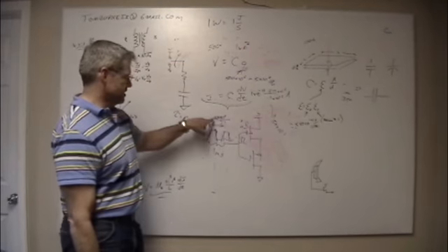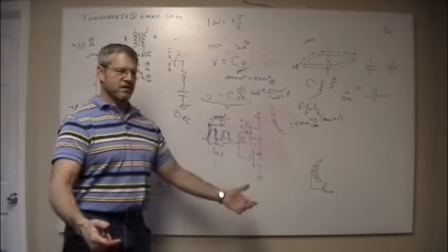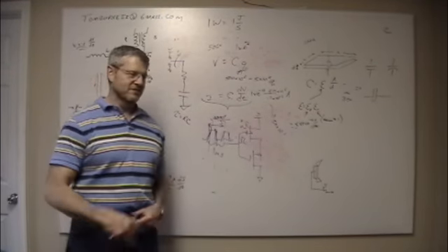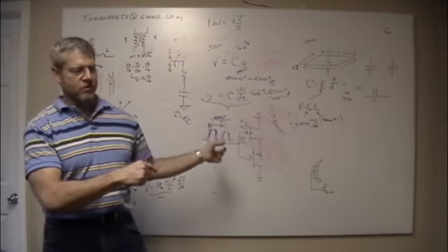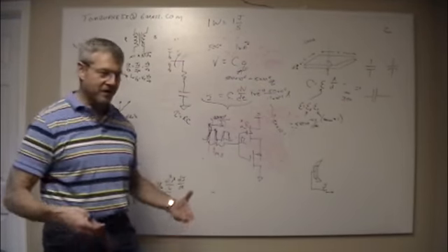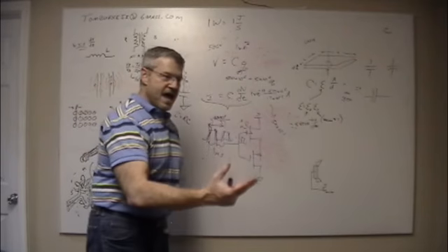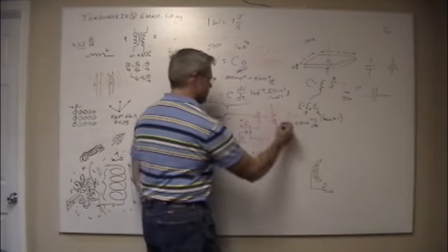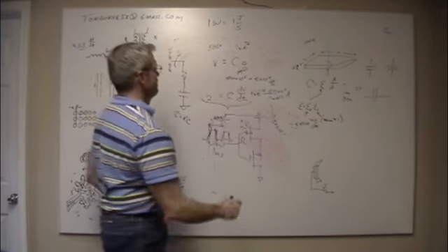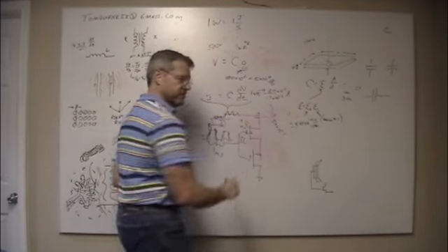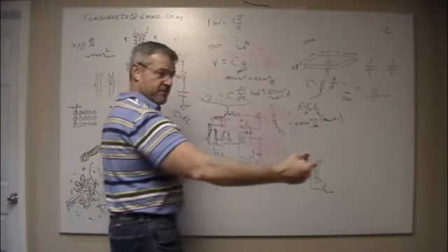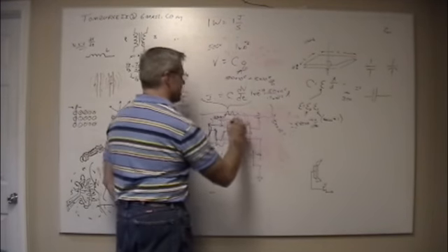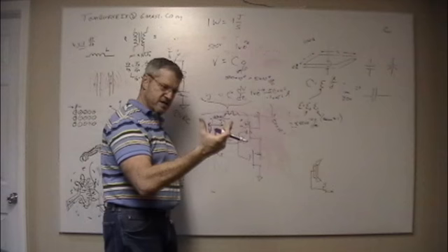Oh, but wait a minute, it's not running at a megahertz, it's running at a gigahertz. So add 1,000 to that, right? I'm in the wrong order of magnitude here, but you get where I'm going. So now I've got 400 gabillion of these things that decide to switch at once, and this power rail up here that's trying to supply all of this has some resistance in it, even though before we said there's none, but we just explained how this copper trace has some resistance. Now I get all this current moving through this copper trace, which gives off heat for one.